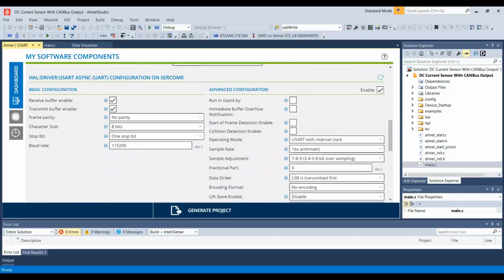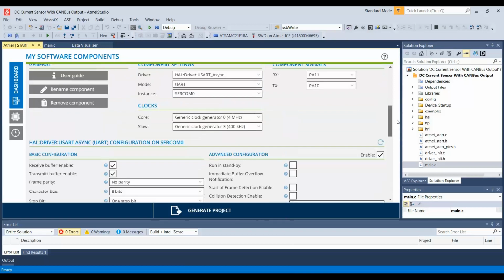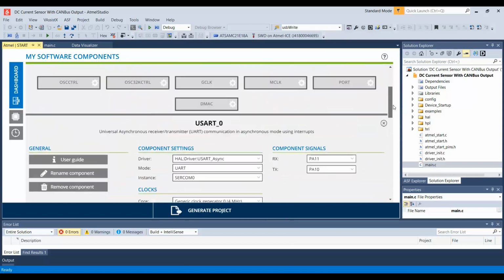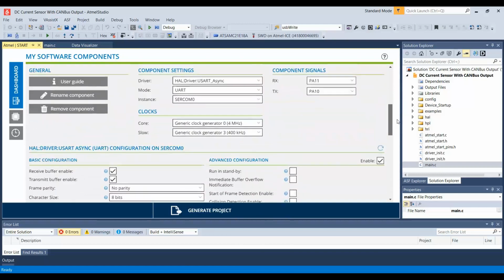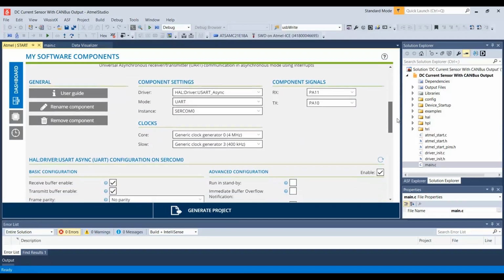Previous to this, I also upped the speed of the port to 115,200 baud because I was getting some glitchiness coming out on the serial port itself with characters being overwritten, but increasing the speed took care of all of that.